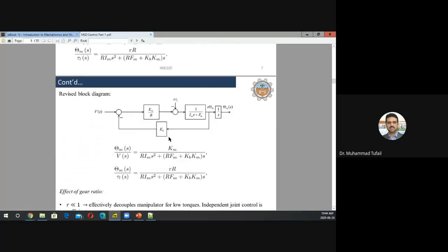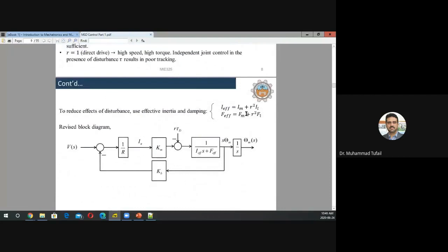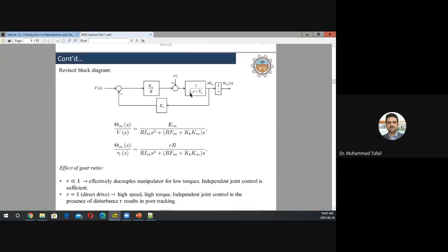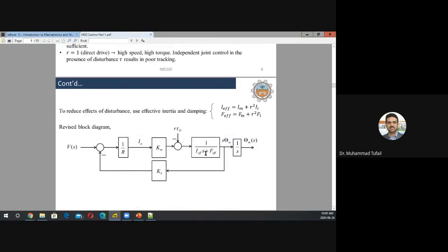So that's another way. So this is the effective inertia. This is the entire inertia of the system. The motor inertia, all the inertia on the systems have been combined, and we have plugged it in here. So we're not only talking about the inertia of the motor, we're talking about inertia of the whole system, and that has a considerable effect on the system time constant, because when you give it an input, you want the system to show response.